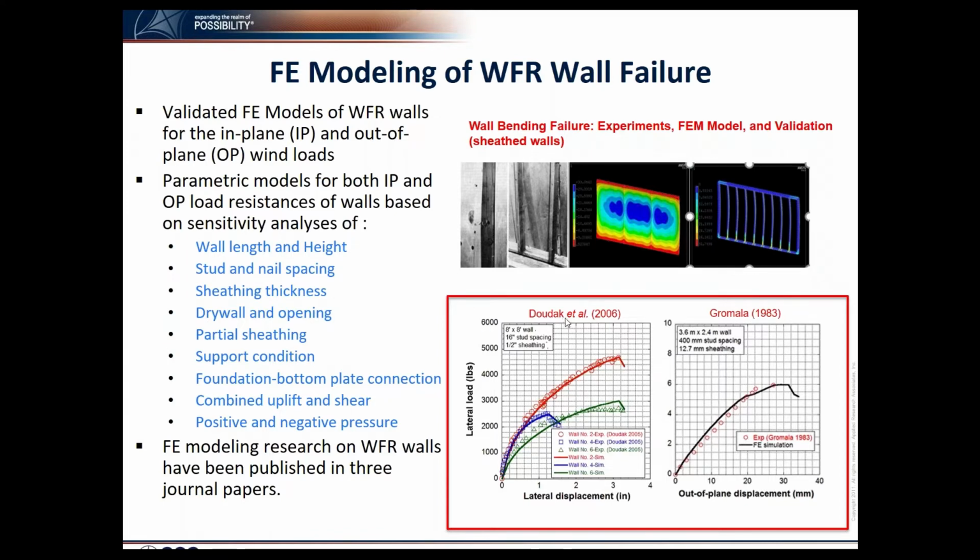We validated our results with the experimental studies, and here it shows our out of plane model and the in plane model match reasonably well with the experiments. We then ran a lot of sensitivities such as varying the wall length and height, the stud and nail spacing, the sheathing thickness, whether there is drywall present, how much opening there is on the wall, whether the wall is minimally sheathed or fully sheathed, what the support condition was, and so on and so forth.